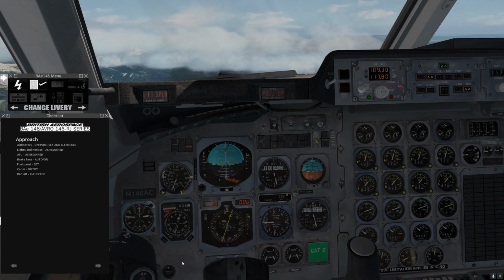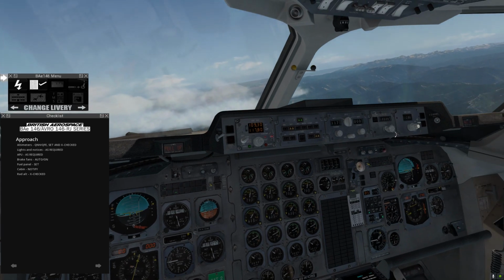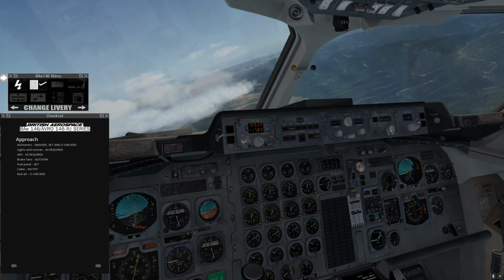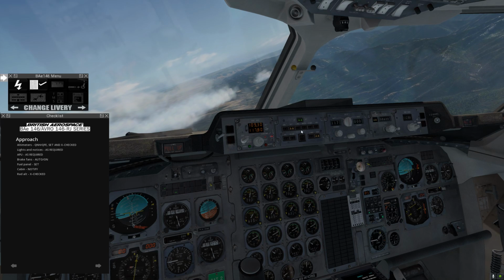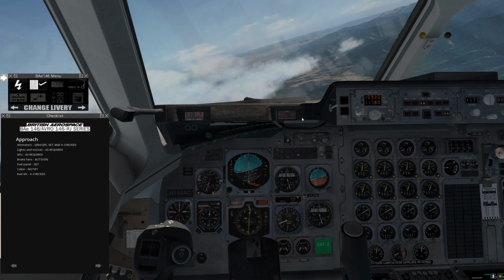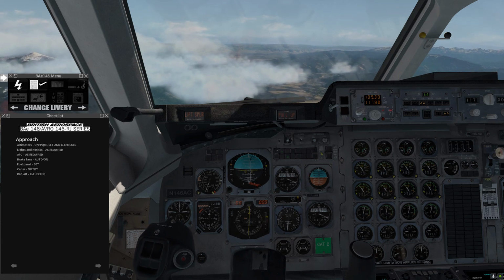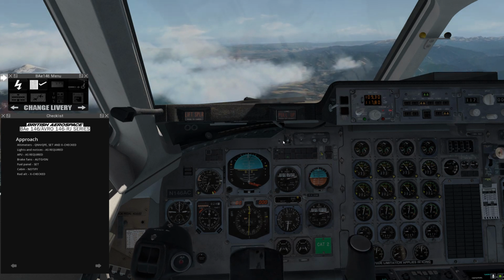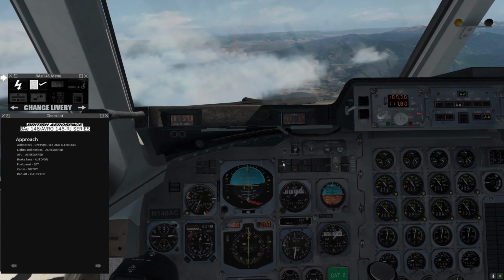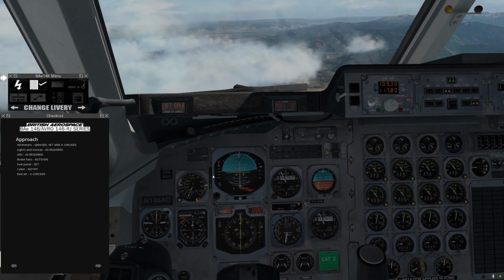Now, interestingly, we see the glide slope is already alive, so we're going to have to duck down below that before, what's the next? The next one is Jeleg. So, just about there, I'm just going to go ahead and turn us now. And we're going to set in our next altitude, which is 8,600. So right about there. Arm, vertical speed, and we're going to use the sync button. And I'm just going to decrease the throttle, and we're going to plop right on down there at about 2,000 feet per minute. We're going to kind of drop quickly here. Let go of the sync button. Now the autopilot should be maintaining that vertical speed. And I'm just verifying we have the new altitude armed. It's white there. Okay.